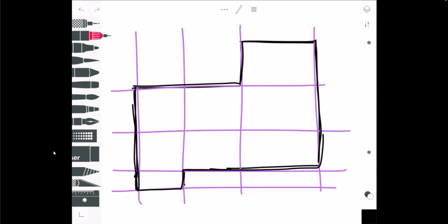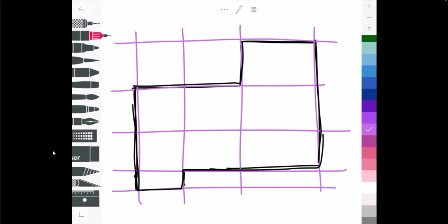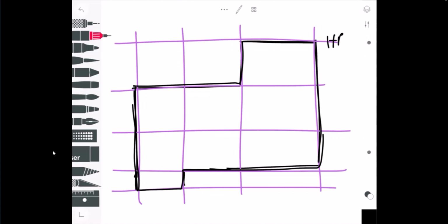Okay, we'll just look at one more example here where I just drew in a more odd shaped building just to see what happens here. So I'm going to draw my high points and low points, and now again I want the perimeter walls to be the high point. So in this point, and this would be a high point, right? I don't want that to be a low point there because I want this wall to be a high point. So I'm just going to look at that for a second and say, well, no, because if I made this a low point right here, I might have a low point right there, which I don't necessarily want. So I'm just going to say high point, low point, and high point.